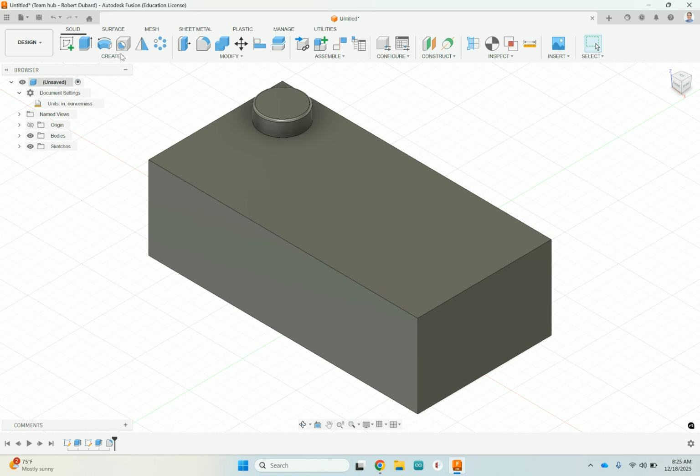What I'm going to do next is under the Create menu, and this is a feature. You'll notice that, let me point this out. I have a sketch, and then I did a feature building off of that sketch. But then next, I just did a feature without a preceding sketch. Every sketch should be followed by a feature in most cases, really in all cases for this class. But not every feature has to be followed by a sketch. Sometimes you can take a feature and do another feature atop it. We're going to do yet a third feature that just builds off existing features.